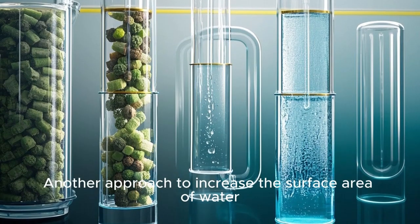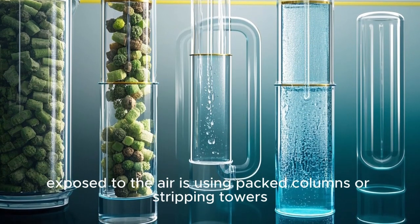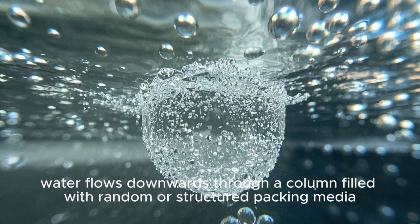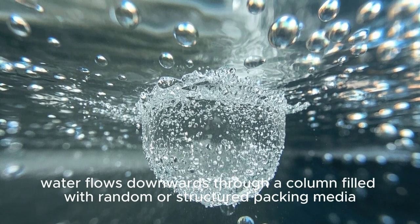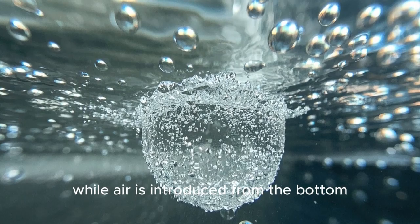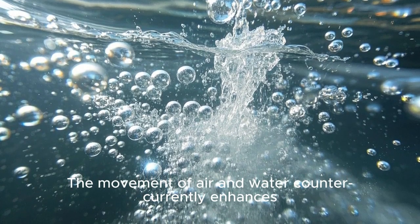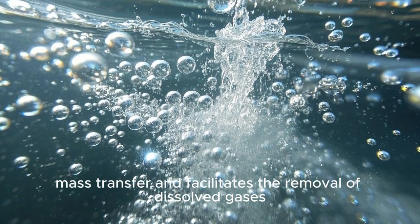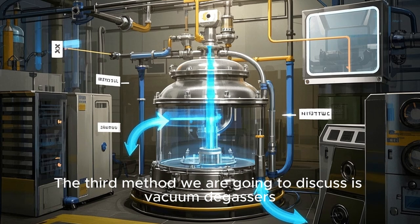Another approach to increase the surface area of water exposed to the air is using packed columns or stripping towers. In this method, water flows downwards through a column filled with random or structured packing media while air is introduced from the bottom. The movement of air and water counter-currently enhances mass transfer and facilitates the removal of dissolved gases. The third method we are going to discuss is vacuum degassers.